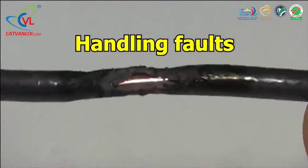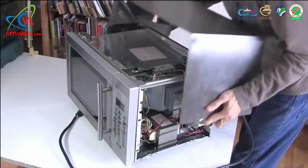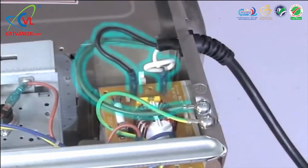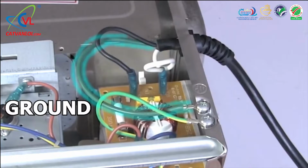That's in case you have a break in the insulation covering a wire somewhere. That break can cause a fault, such as in this microwave oven. Three wires enter the microwave oven. Those three wires are connected to the three prongs of the plug: hot, neutral, and ground. As we said, the electricity flows through the hot and neutral wires. The third wire is the ground wire. The ground wire is connected to the metal case, and normally no electricity flows through.